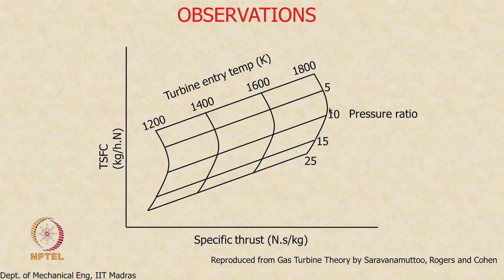So, we have plotted fuel consumption per unit thrust. You can see from here that the thrust increases and decreases, but these increases and decreases are actually much less than the changes in the fuel consumption, which is why we are able to infer this trend from this graph also. We did not have specific quantities in the previous TS diagram. We had only other quantities, but the trends that we are seeing here are consistent with what we saw earlier.